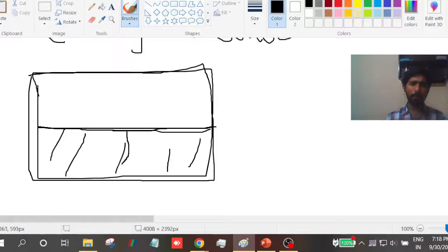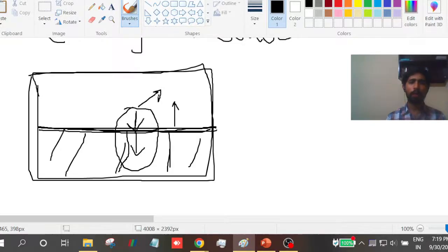But one thing is, when you cross this interface, you take into account whatever different material properties are coming, but you also need to take into account the interface itself. There are some forces which act on this interface, and the reaction force is built by the other fluid which is there. So this is usually the surface tension force which comes into the picture. These are taken into account using a source term in the momentum equation. So you have to take two things into account: one is the difference in the material properties, and then this force term on the interface. You have to take that into account in the governing equation itself. That is how you come up with a one fluid approach.